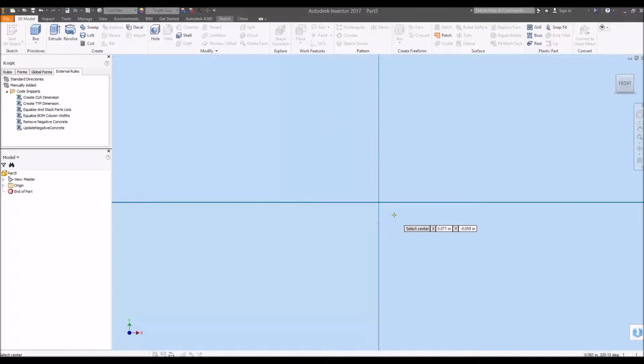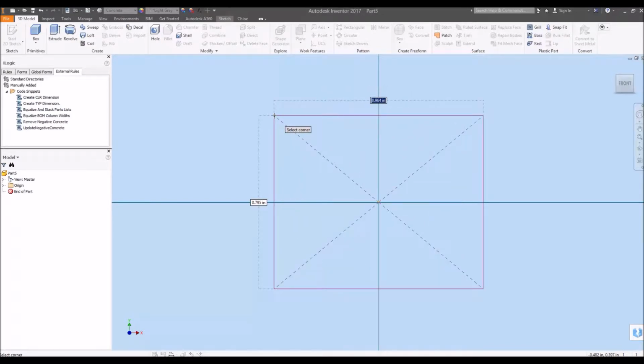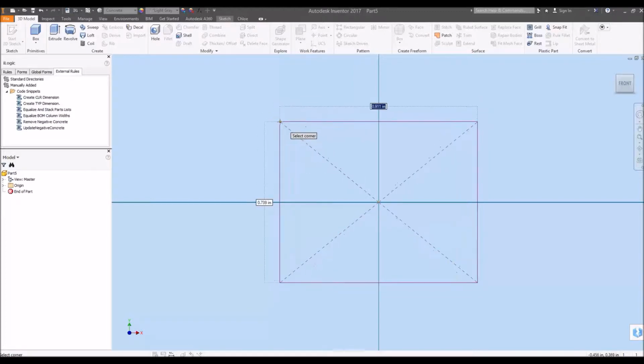Once you're in sketch mode, let's go ahead and choose the center of our box. Just like AutoCAD is asking us with a prompt, either in front of us near your cursor or on the bottom left-hand side of the screen, to choose your operation. So after I select my center point, I'm going to drag my cursor into the upper left quadrant, and notice how the dimension on that horizontal line at the top is highlighted. This means that it's prompting us to enter that information.